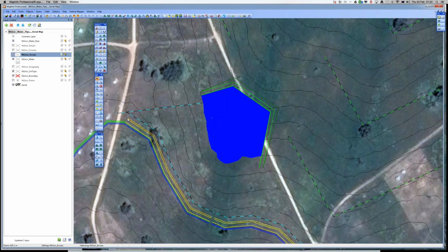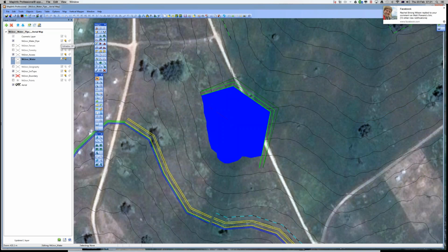and now it becomes selectable, and you can Control X and cut that item, and then click where you want it to be. So for example, let's say I'll take these pipes out and I want to put them in the water pipe layer. First up, I'll click the water layer and I'll click Control X and they'll disappear.